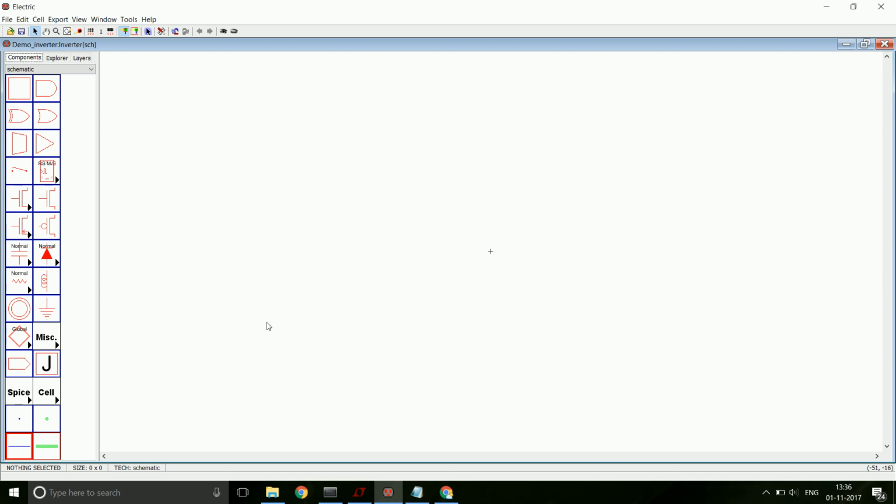The W by L for NMOS is 6.16, and for PMOS is 13.31. So let's tick the PMOS and then NMOS.